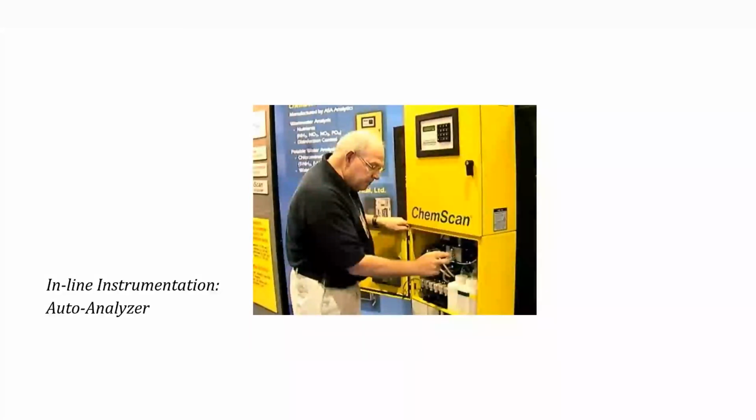The very best way, and I love these instruments, they're expensive. They're quite expensive. They can be six figures, $100,000 to get an auto analyzer inline. But some of these inline instruments will measure multiple parameters from multiple locations and track and chart it all for you. I saw one in Virginia that takes samples from 4 locations and does soluble phosphorus, the orthophosphate, does nitrate, does alkalinity, does ammonia. I forgot what else it does, and tracks all that. Great tool. As the numbers get more restrictive, a $100,000 investment actually looks pretty attractive.